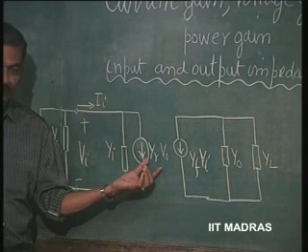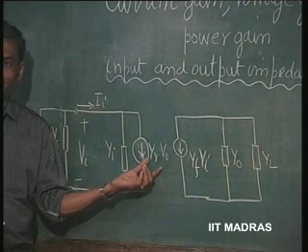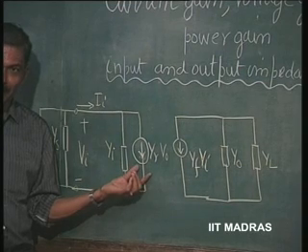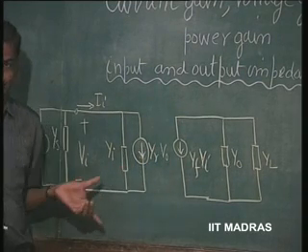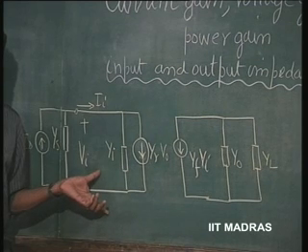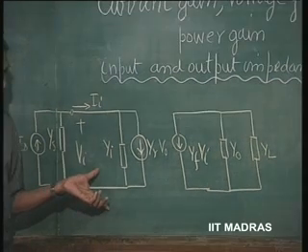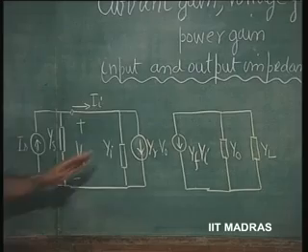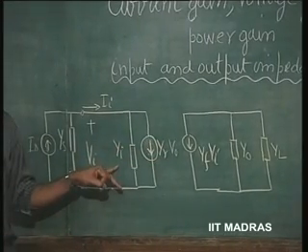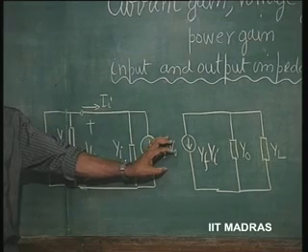What is this going to do? This is going to give us a lot of trouble. This is unnecessary feedback from the output. This is going to interfere with our input. So, how it is going to interfere with our input, we would like to see. So, obviously, the input impedance earlier without this was simply determined by Yi, 1 over Yi, if this is not there.